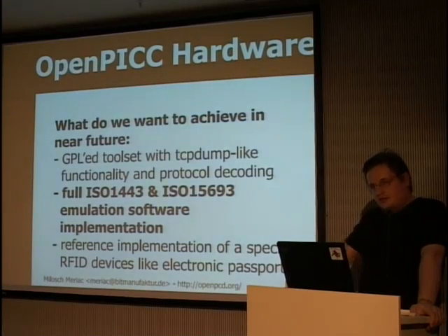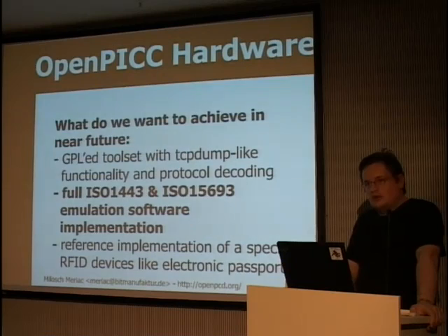Yeah, and as soon as the basic ISO 14443 and ISO 15693 support is up, it's very simple to add emulated card profiles. Because we have plenty of space there, you can even emulate multiple different cards with the same device. So as soon as they're documented, it's only a matter of hours or days to implement such a protocol, if you have the bit layer set. So say anti-collision and the modulation and demodulation.